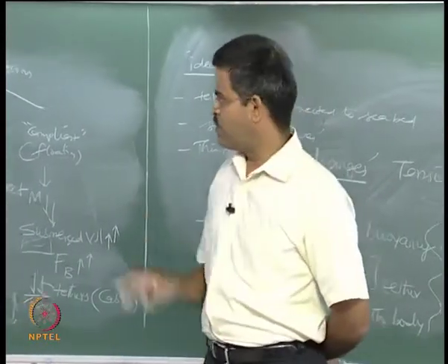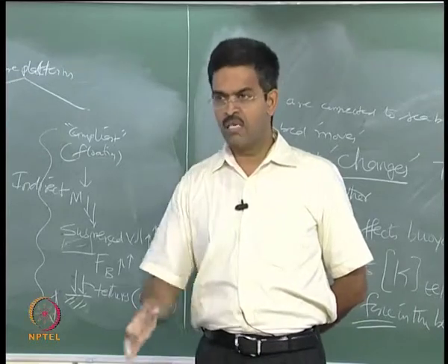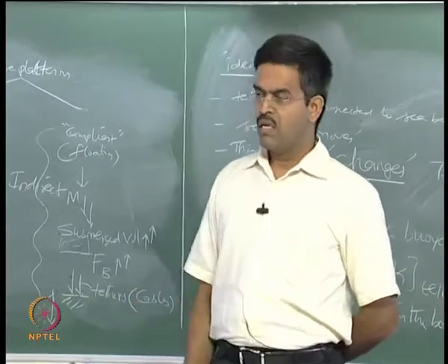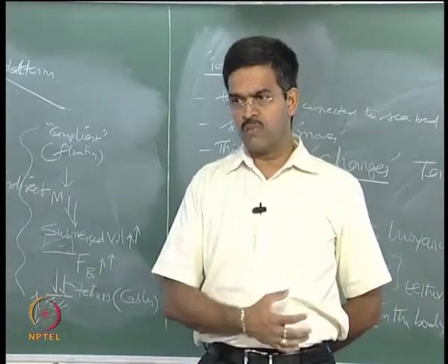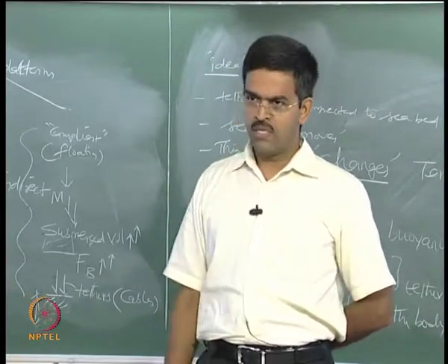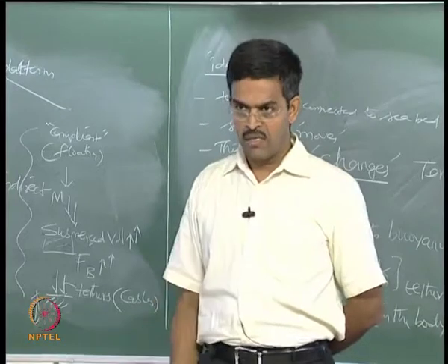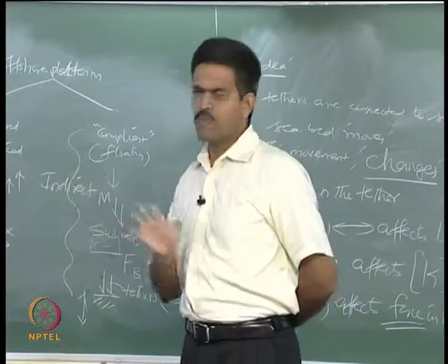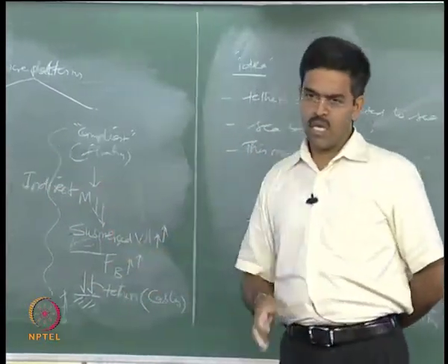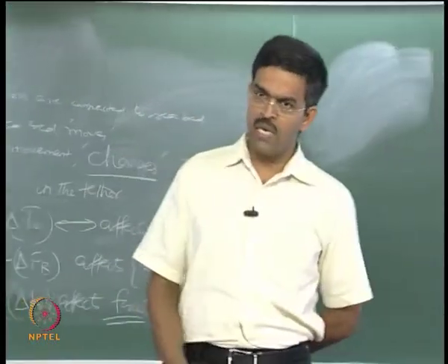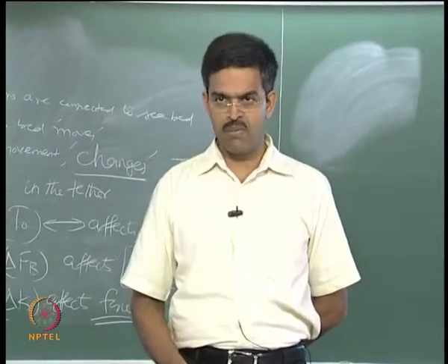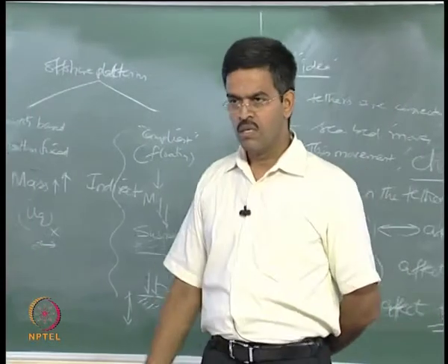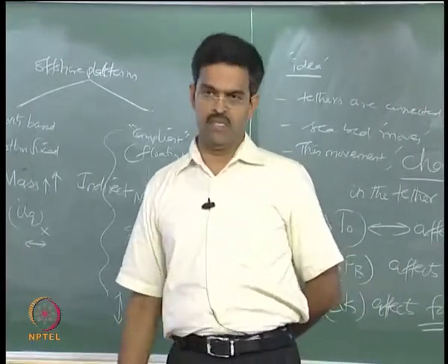The third application is deep water risers where directional drilling is taking place. In between the riser segments I have to hold down the riser profile, otherwise risers will be subjected to a lot of lateral forces because of current and waves. To improve on the dynamics of risers, I support the risers in between using this kind of structure. There are segmental applications for this. Obviously an AT cannot be a production platform, but surprisingly ATs have also been attempted as production platforms, which I will show you in the next lecture. A couple of production platforms have been attempted in the US and Gulf of Mexico using multi-hinged, multi-legged ATs, MLATs.